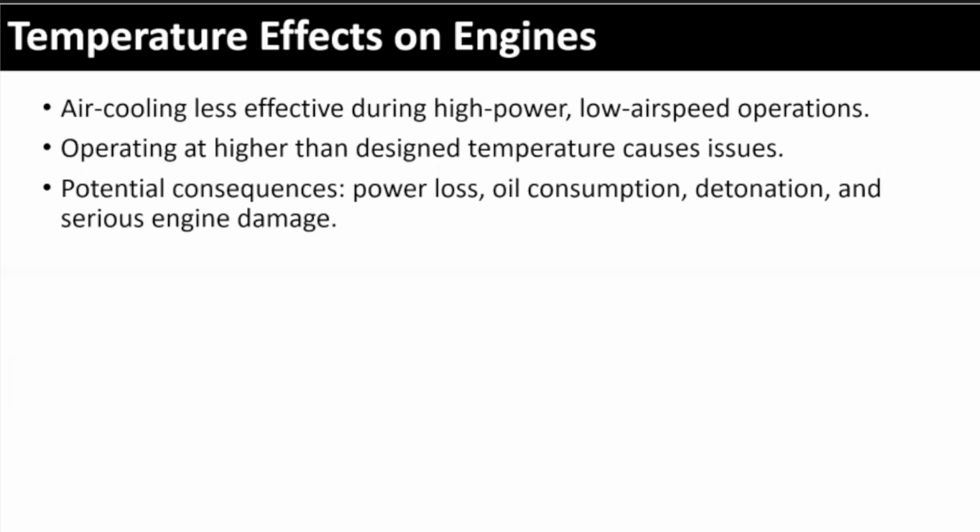Situations where you can't avoid it, like in a steep climb, right? High power settings, low speed. What do we do to help us assist? Nose down, right? So if you're in an extended climb, just lower the nose, let the airflow cool the engine down, and then continue your climb. Okay, get that airflow, let the air do its job.